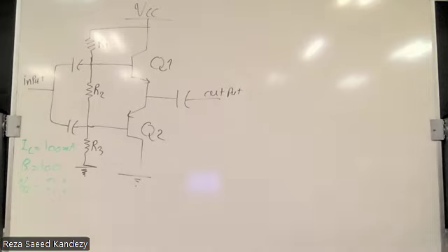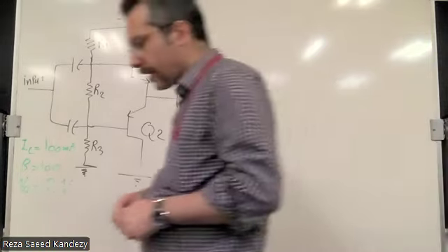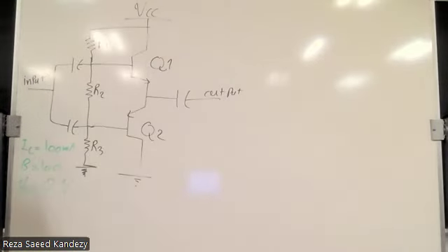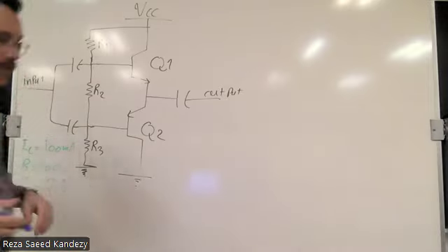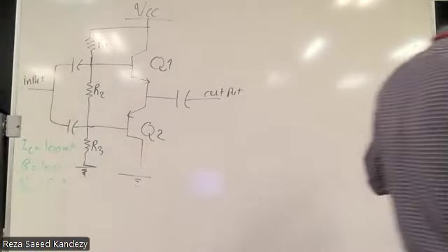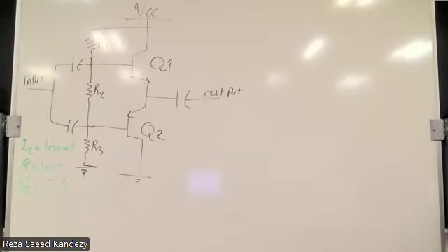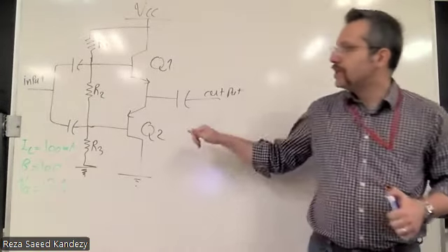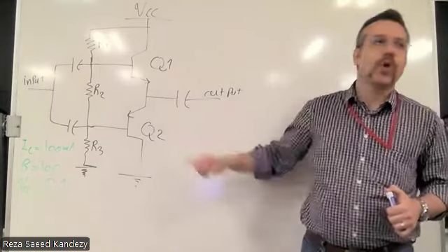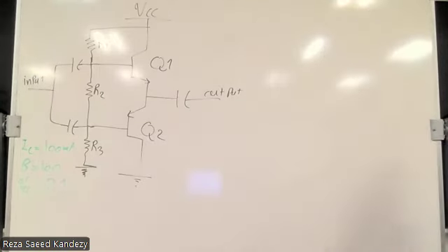Now, today we are going to talk about the Class B and Class AB amplifier and how we can design the Class B, which is basically the base of Class AB. There is a very little difference between the two, which we are going to talk about. Now, the Class AB amplifier, as we talked before, basically contains two switches, one NPN, another one is PNP.